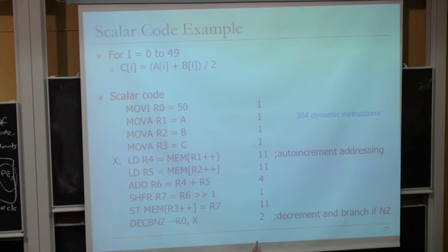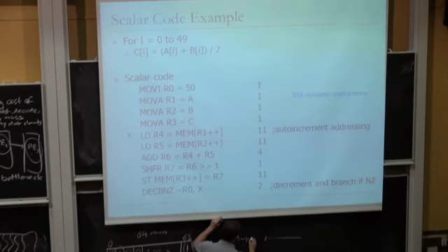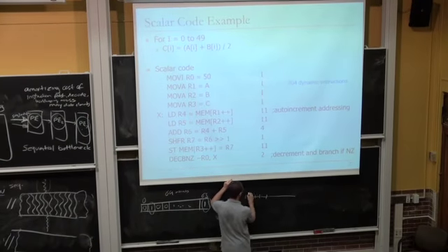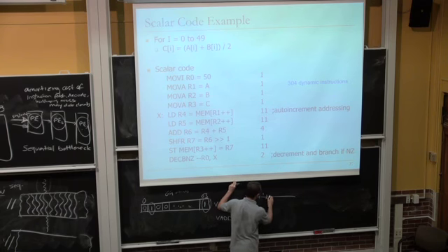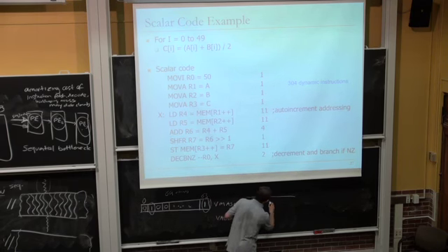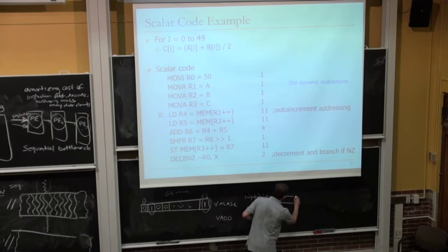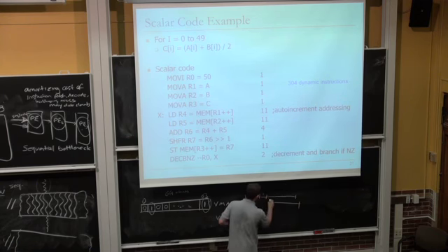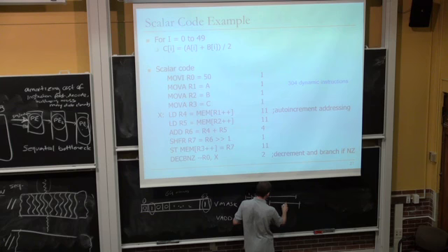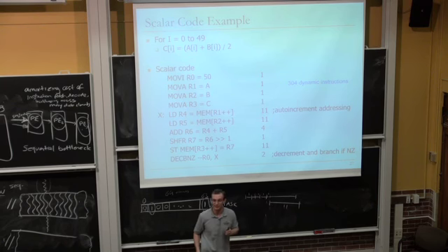You can start the first load at the end of the 4th cycle. So your execution time 1, 2, 3, 4, the first 4 instructions. And then you can start the first load. In the next cycle, you can start the next load because you have 16 banks, and these are 2 consecutive words, which means that you can overlap the latency of these 2 loads. Right? So these 2 loads together, if you will, take 1 and 11, 12 cycles.